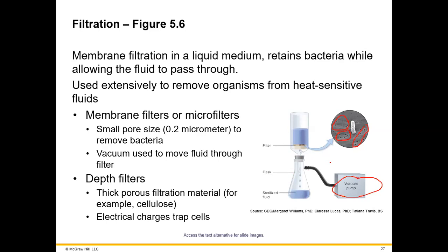Here, the size of the pore can be controlled. The manufacturers have engineering techniques to control the size of the pore. The standard size that we use in the lab is 0.2 micron pores. Too small, of course, for any bacteria to go through. Even some large viruses can be retained. So these are the so-called membrane filters. It's a very thin membrane, typically around 1 millimeter or thinner.